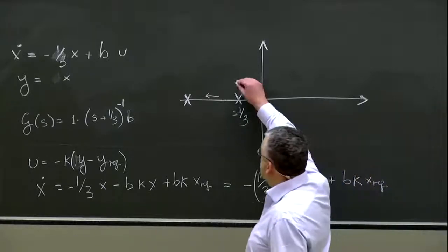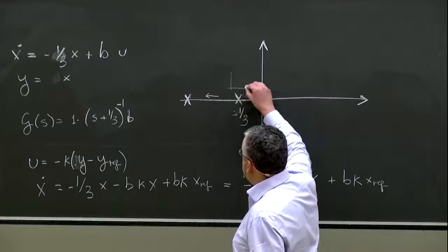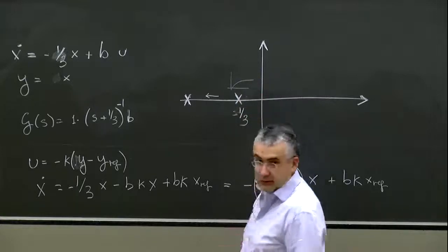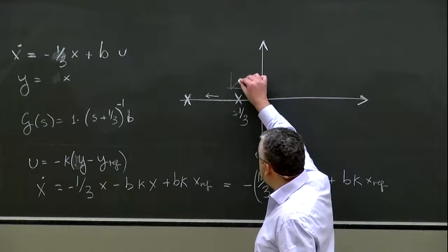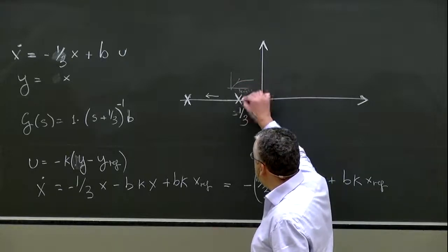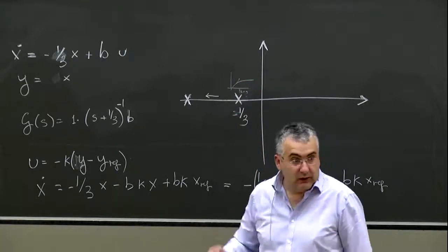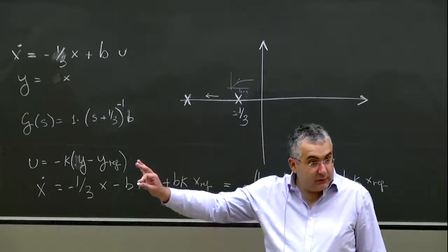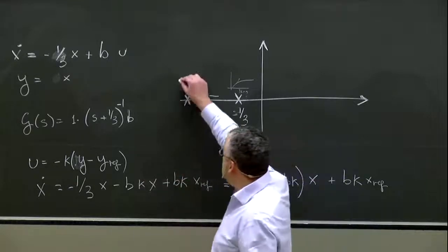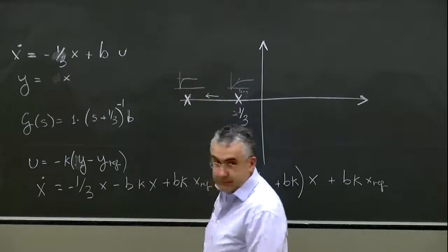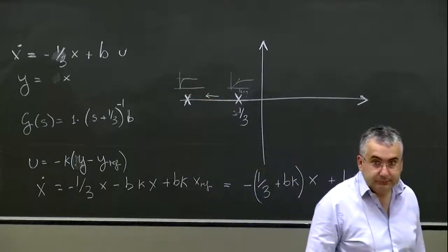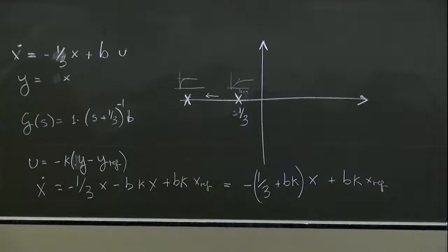The step response was something like that, right? With a time constant of 3 hours, right? If I move the pole to the left, what it means is that I still have exponentials, but the exponential will be faster. Okay? You see what is happening?